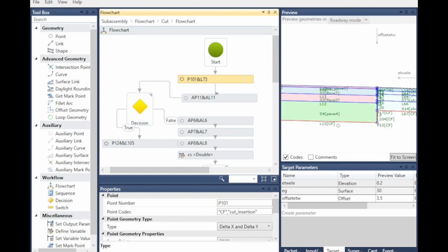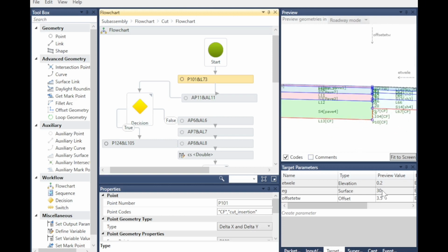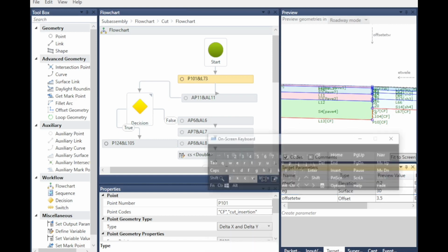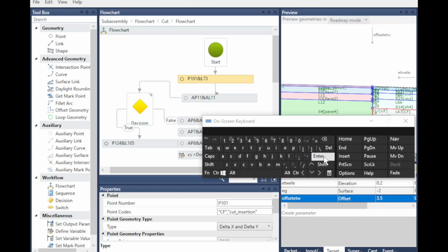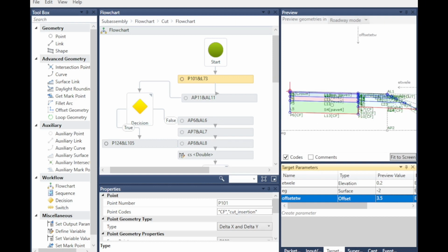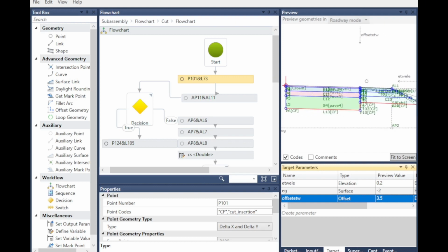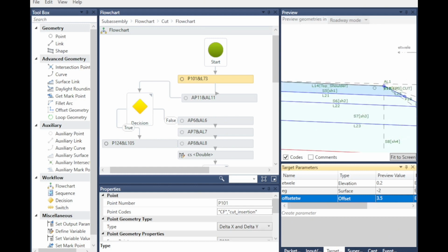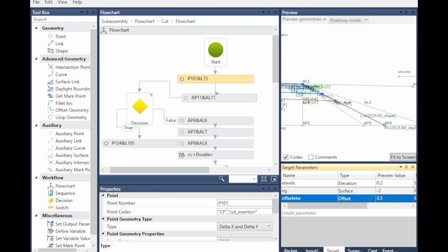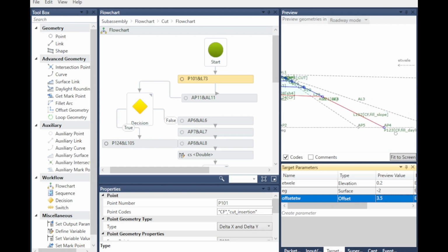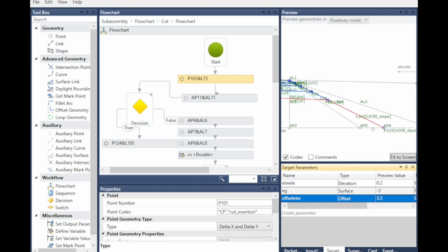We had again given CF, which means cut fill for all datum links. Datum code is similar in fill condition. Fill daylight code for the point and fill slope for link.